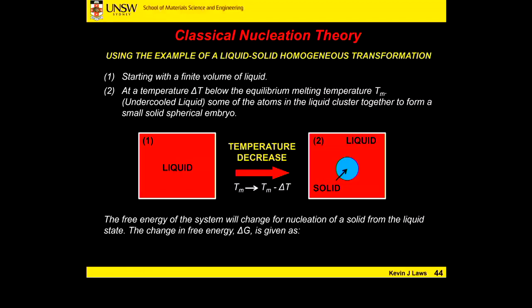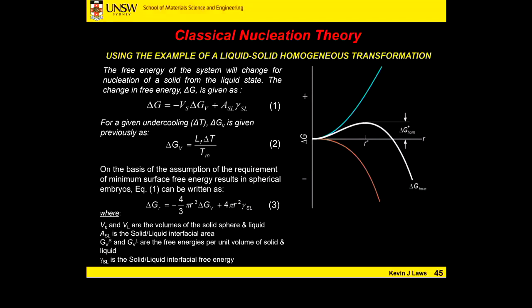We looked at classic nucleation theory, defining a solid or another phase emanating from another phase within a fixed volume. We looked at the simple example of a spherical embryo of the new phase forming, and we were able to define in terms of its critical radius the driving force for its formation and continued growth or stability.